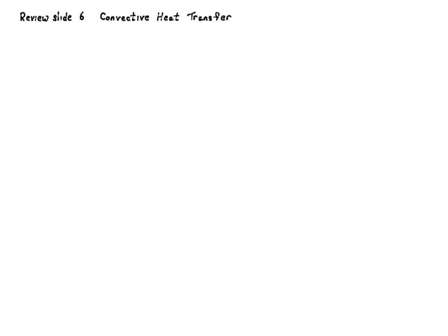Okay, what we're going to cover in this review slide is convective heat transfer, and just a tiny bit that we've covered with regards to how it applies to our analysis of conduction. Now, what we're going to utilize is Newton's law of cooling, which is given by the heat rate is equal to some proportionality constant times an area times a temperature differential.